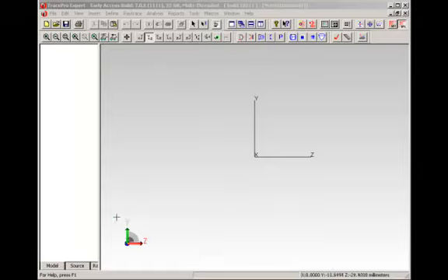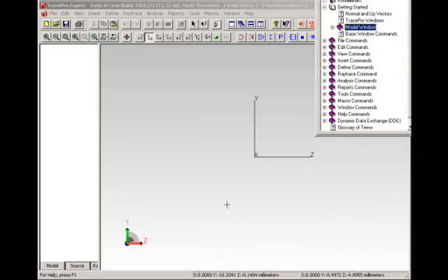In the bottom left-hand corner of the system view is the XYZ global axis, and in the middle is the 000 XYZ local axis. Down the bottom right-hand corner, we have the status bar, which shows us the XYZ position anywhere we put the cursor. If we left mouse click, there's a static definition for the XYZ as well. At any time, you can hit the F1 key to get help on any of the various sets of information in the program.